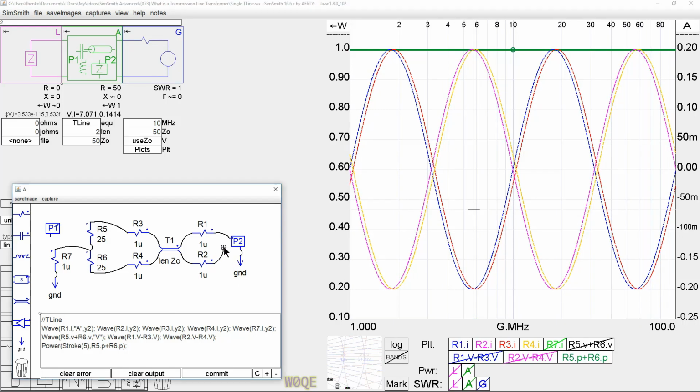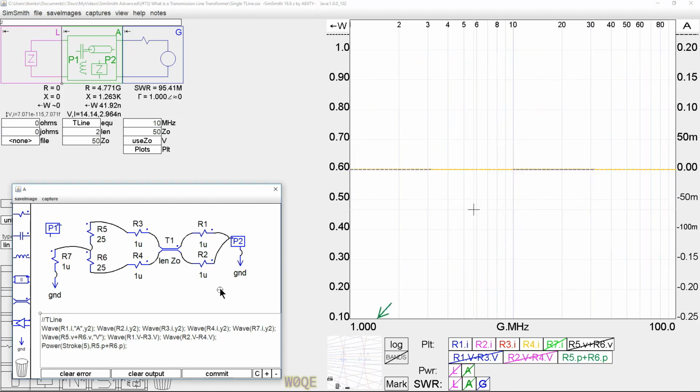is we'll drive both sides of the transmission line from the same point with respect to ground. We have the output connected to ground. Now, there's 25 ohm resistors in there, so we'd expect to see a 25 ohm impedance on either side if there was no common mode impedance here. If there's common mode impedance, we'd expect to see something less. Let's look at what we see. And we see R1, R2, R3, R4, all low. Let's look.